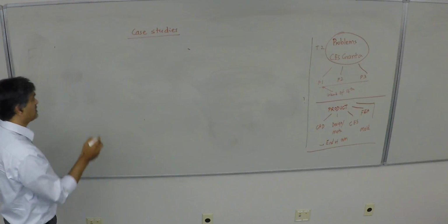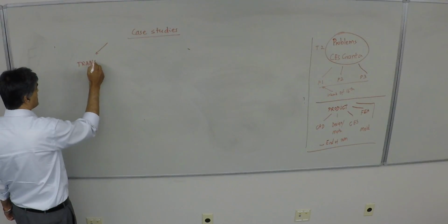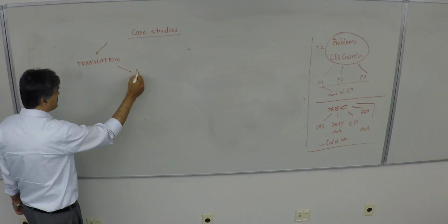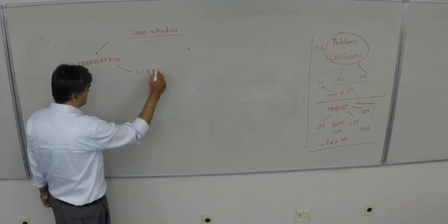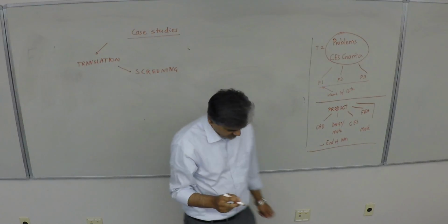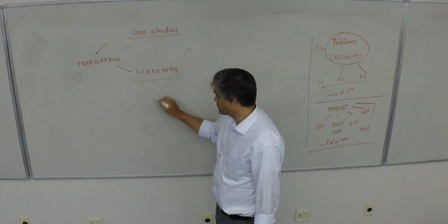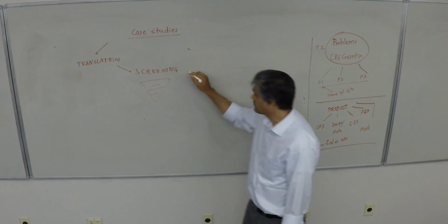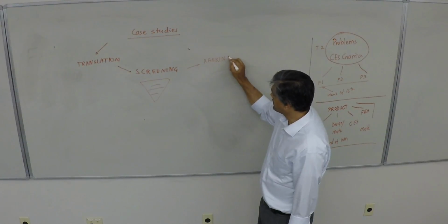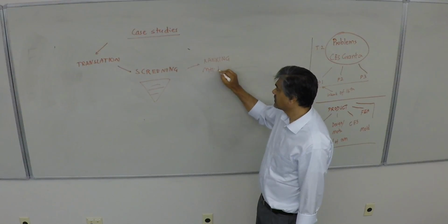First I gave you the approach to translation, and then from translation, once you set that up, you do screening, of course, in terms of reducing this, narrowing down the choices, if you will. And then from screening, you're doing the ranking, where you incorporate the material indices.